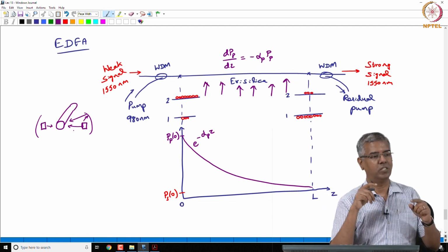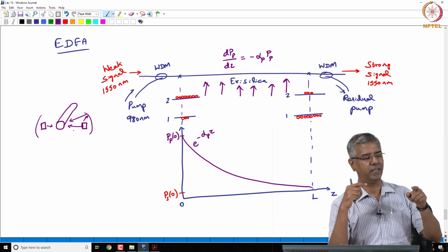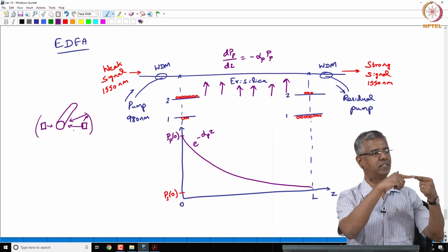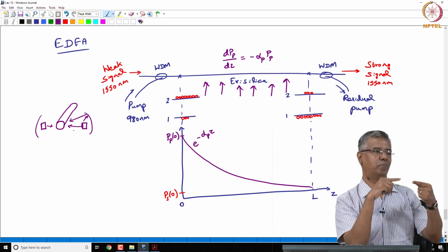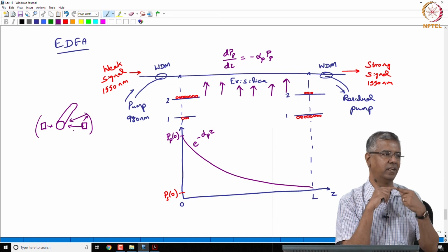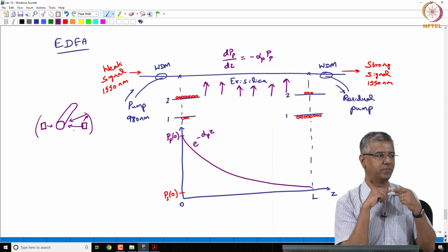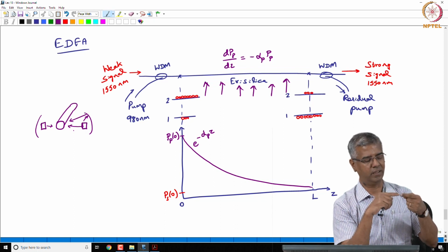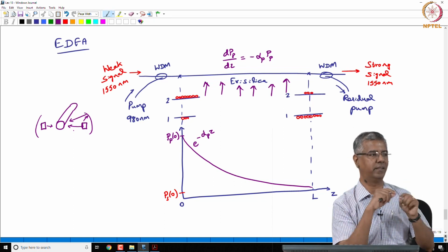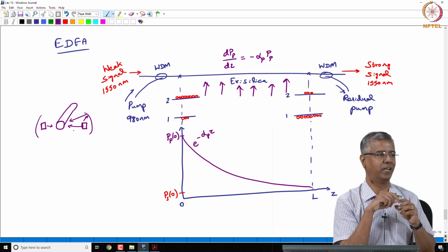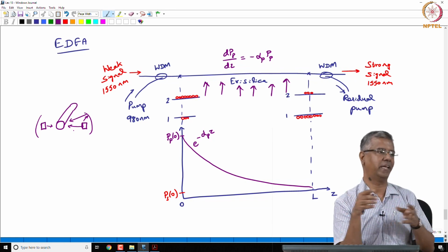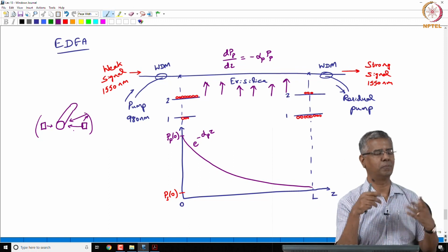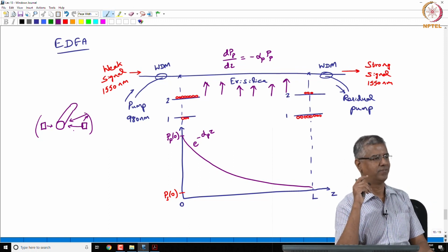So, you have the possibility of taking the fiber. If this is my semiconductor laser, I take my fiber and just directly butt couple it against my semiconductor diode, right. So, I just hold it right against that aperture, so I can couple light directly. I do not even have to think about taking the light out and having some focusing optics and coupling it, because the packaging, that would be a mess, right.